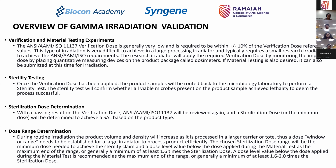Now you will ask me a question: why take a chance? Why can't I just go to the higher limit and fix the range? Again, if you fix a range at a higher level, and if any value falls below that when measured in a manufacturing process, or the tunnel actually, when it moves through the tunnel, through those hairpin bends, if at any given time your dose falls below the specified value also, you cannot accept the material as sterile. So that is the reason you always provide a range, just like we did in temperature.